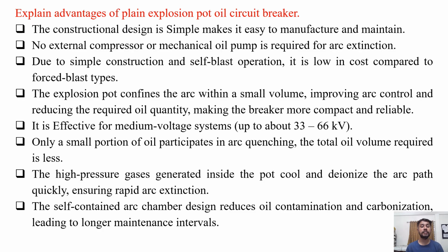The high pressure gas is generated inside the pot and deionizes the arc path quickly, ensuring rapid arc extinction. The self-contained arc chamber design reduces the oil contamination and carbonization, leading to longer maintenance intervals. So these are several advantages of plain explosion pot oil circuit breaker.